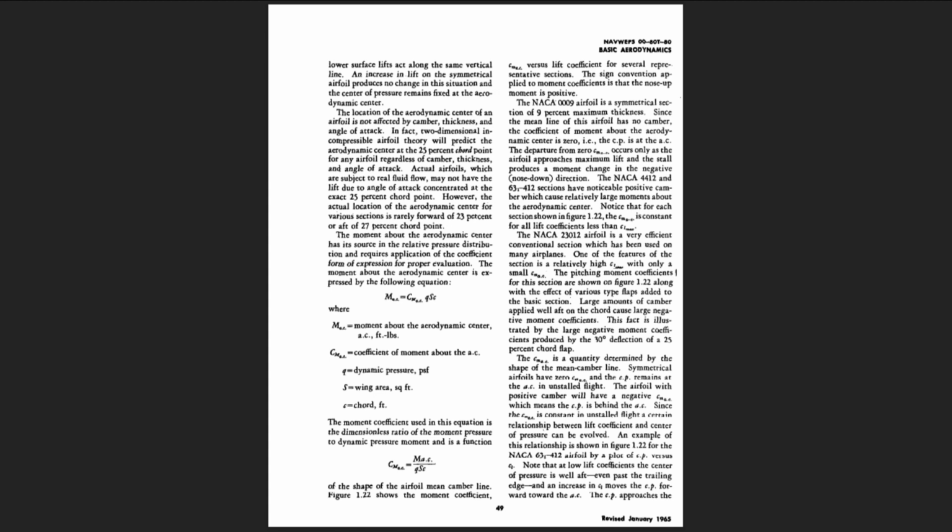However, the actual location of the aerodynamic center for various sections is rarely forward of 23% or aft of 27% chord point. The moment about the aerodynamic center has its source in the relative pressure distribution and requires application of the coefficient form of expression for proper evaluation. The moment about the aerodynamic center is expressed by the following equation.